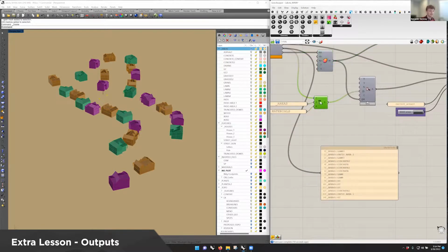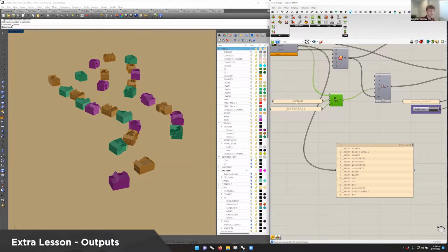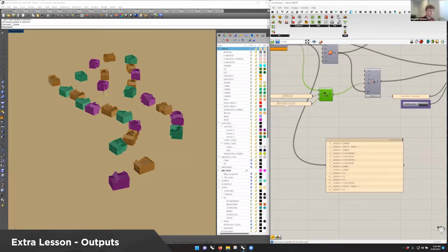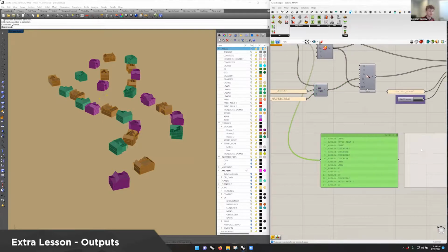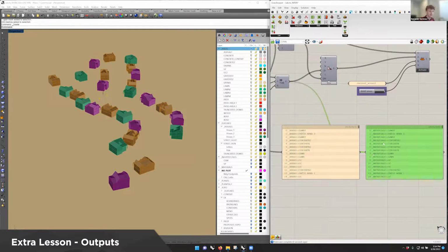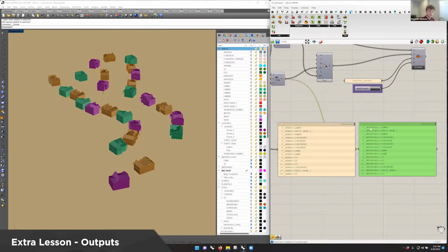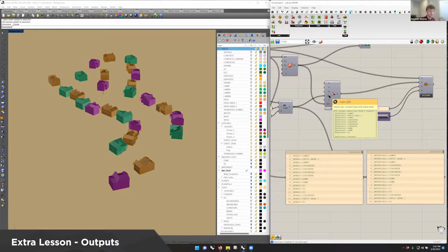And what we've done is we've taken this native Grasshopper component called replace text, and we're saying find all of the instances of underscore area and replace it with an instance of underscore materials. And what you see coming out of that is a new naming structure where it's all listed as materials. And then that layer structure is being plugged into the layer input of the Elefront attributes. And all that information is being categorized as just a general Elefront attribute, and that is being fed into the attributes input of the bake component.